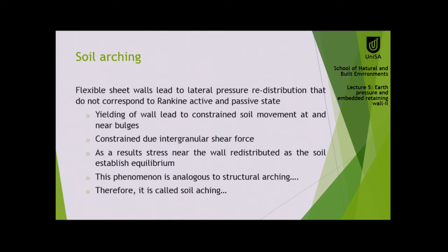As a result, stress near the wall redistributes as the soil establishes equilibrium. So there would be a pressure distribution that wouldn't be exactly the same as Rankine theory. This phenomenon is analogous to structural arching, therefore it is called soil arching. So let me explain in a very simplistic way what happened.